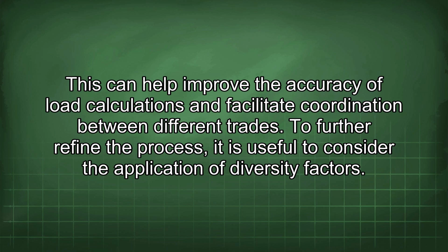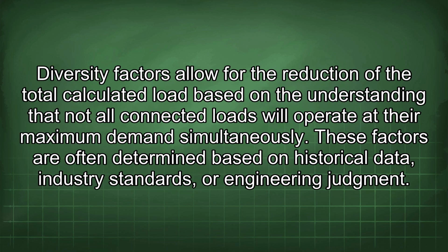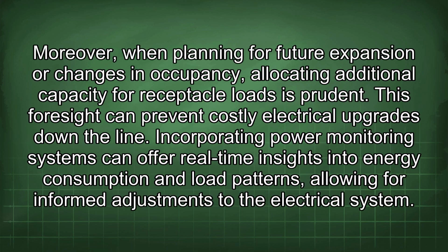To further refine the process, it is useful to consider the application of diversity factors. Diversity factors allow for the reduction of the total calculated load based on the understanding that not all connected loads will operate at their maximum demand simultaneously. These factors are often determined based on historical data, industry standards, or engineering judgment. Moreover, when planning for future expansion or changes in occupancy, allocating additional capacity for receptacle loads is prudent. This foresight can prevent costly electrical upgrades down the line.